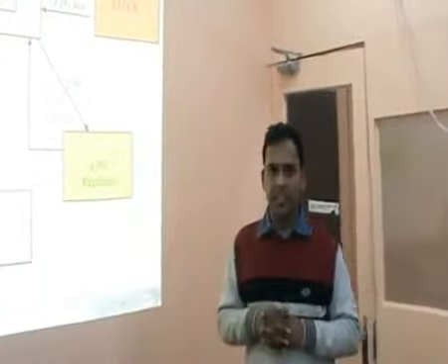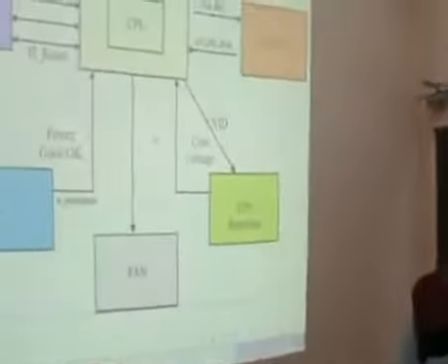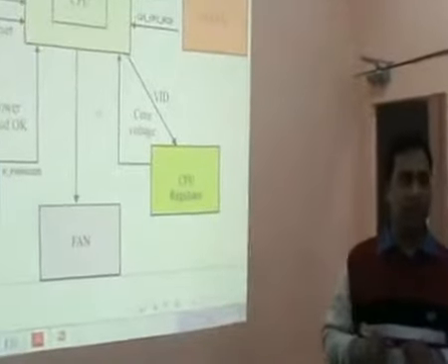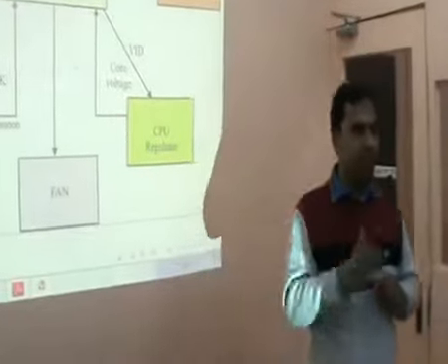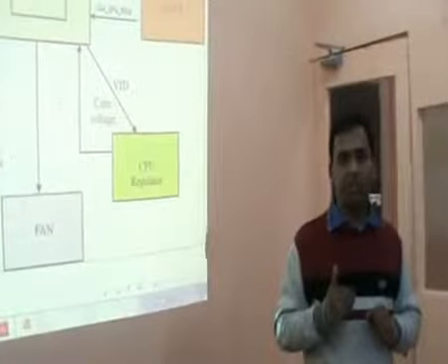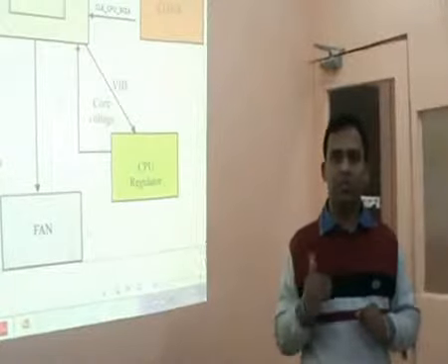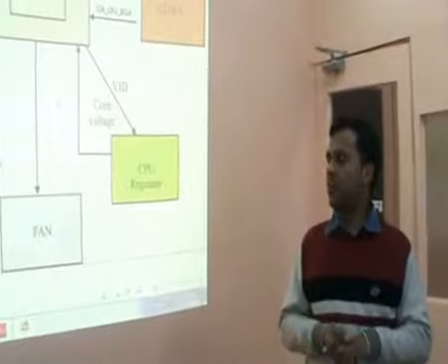In this session we will focus on one laptop motherboard, the DV2000, but the things I am explaining are common to all laptop motherboards. The names of the signals would be the same but their positions would be different. So you have to remember the name of the signal. You must not focus on position. Let's start with the schematic diagram of DV2000.